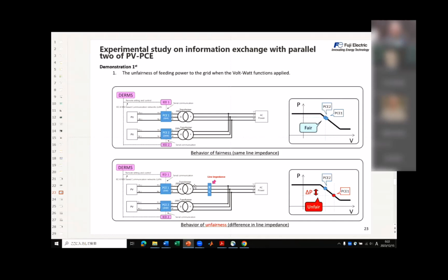So make an adaptive control, not with fixed values, but saying, well, this is a higher percentile of voltage measurements of the last 3 days or so. It's also a different situation, of course, in summer than in winter when there's not much PV. But that would be my recommendation.